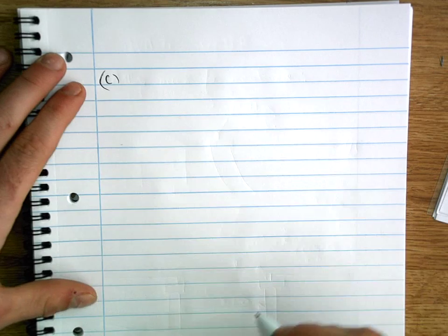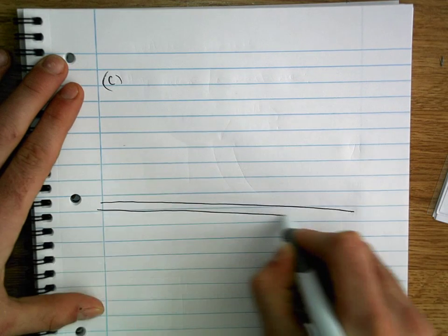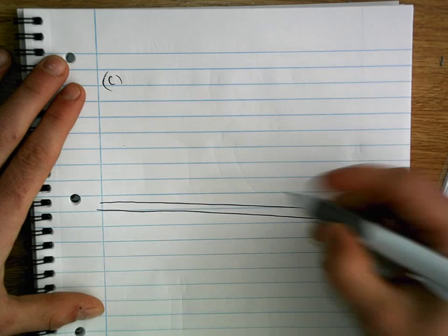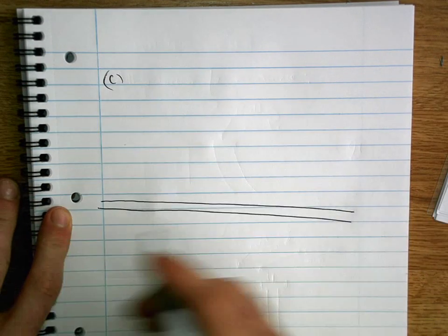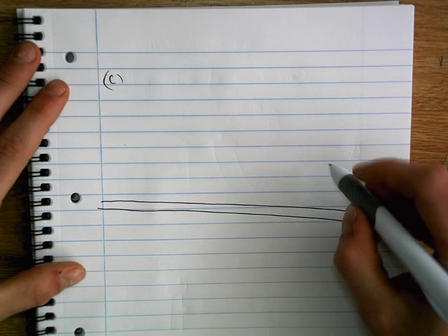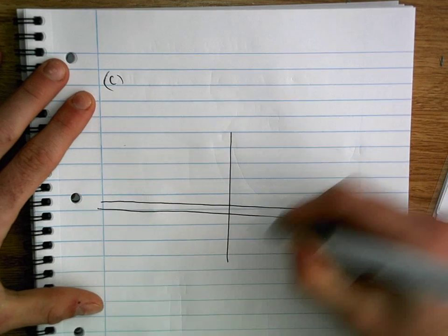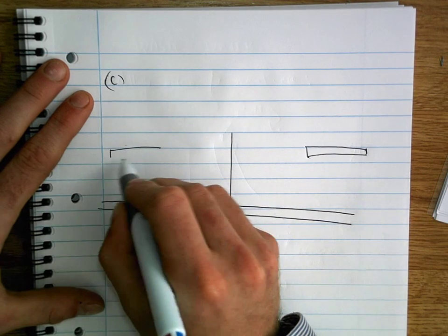So let's say we have a drain running underneath. Again, slope 1 in 40. And what we're going to do is you would have junctions spread across every now and again on your pipe work. So from one junction to the next, we're going to test if there's any leaks. So let's say for argument's sake we just break it there. We'll have a junction on the right and we'll have a junction on the left.